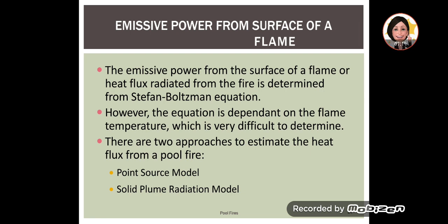Next, to determine the heat flux from a pool fire, the existing equation is very much dependent on the flame temperature, and it's very difficult to determine a flame temperature. So therefore, we have two different approaches that can be used to estimate a heat flux from a pool fire. It can be a point source model or a solid plume radiation model.